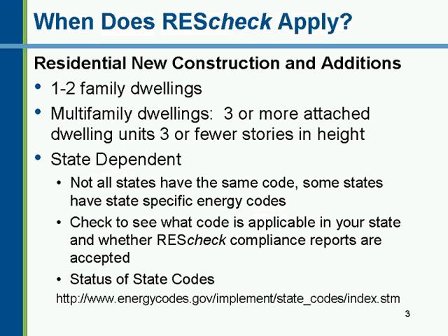And when also does REScheck apply? Well, not every state-specific code is in REScheck. We have all of the IECC codes, and now we have the 2006, which is what we're going to talk about today. But what if you don't know what code is applicable in the project in your location? Then you can go out to the status of state codes and click on the state that's applicable to your location, and that page will tell you what their current adopted energy code is, if they do have an energy code.